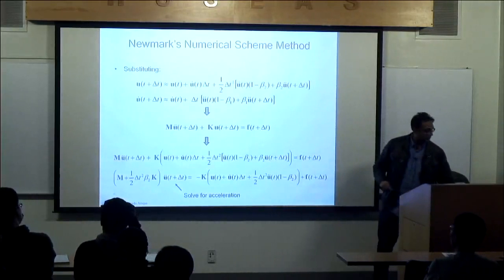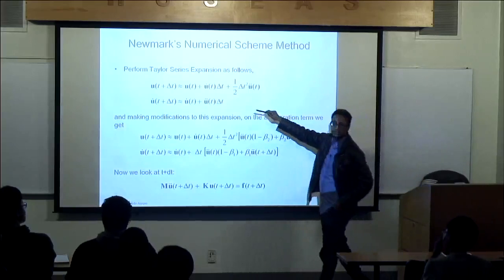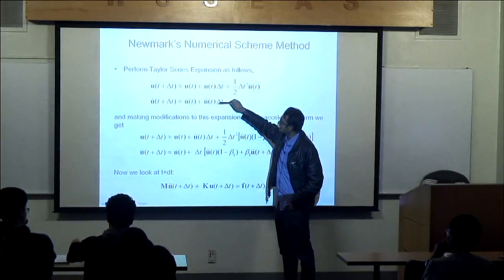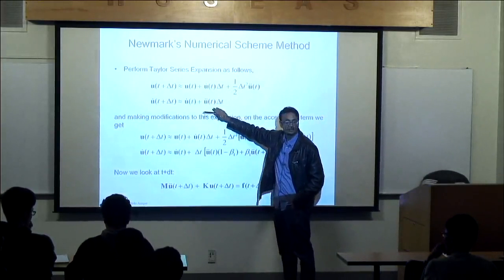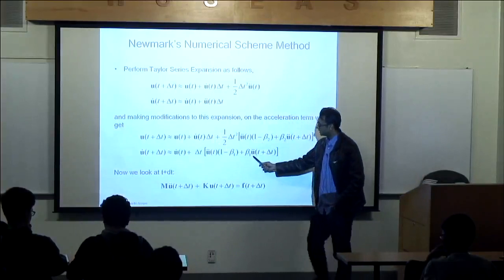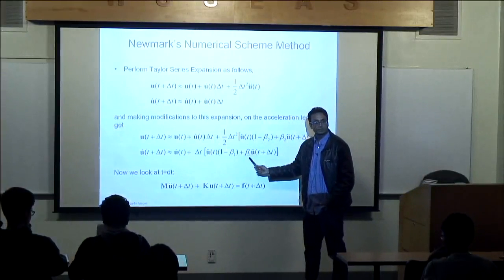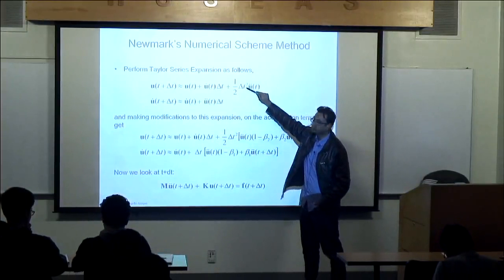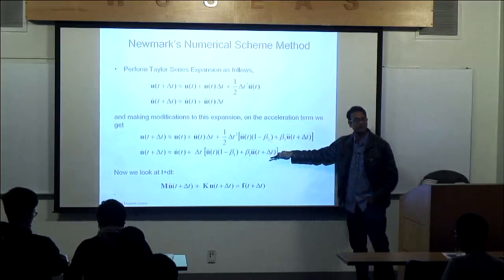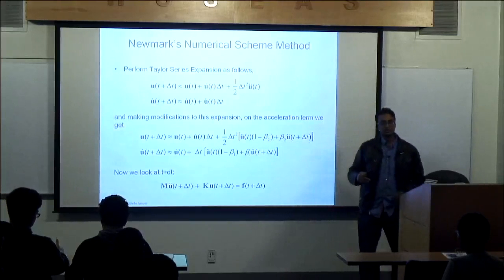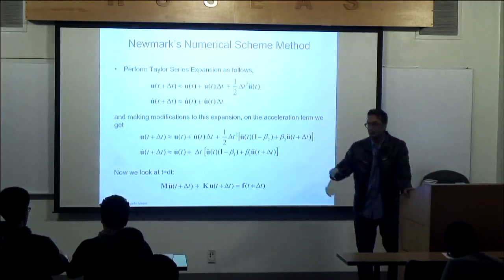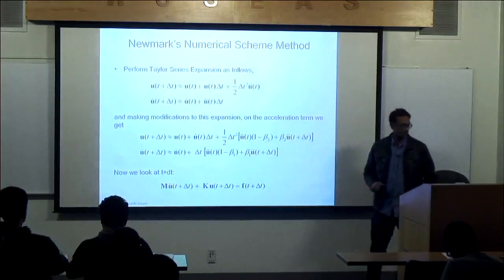I said let's take the acceleration and interpolate the acceleration for the velocity term differently from the first equation, which I'm interpolating with beta 2. So we're just independently interpolating the accelerations between the future and the present for both the velocity term and displacement term.